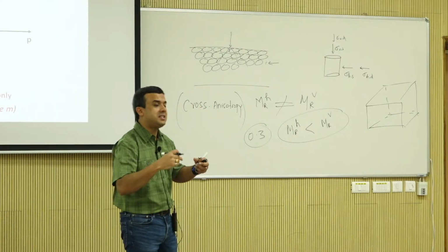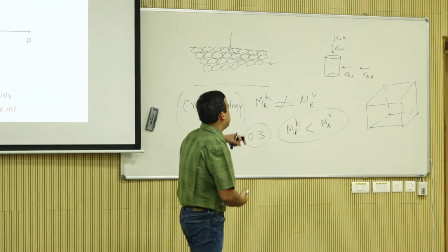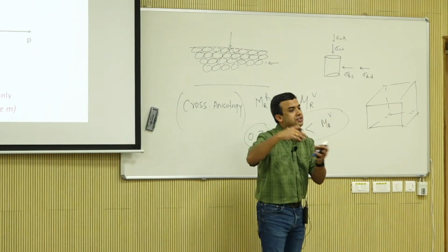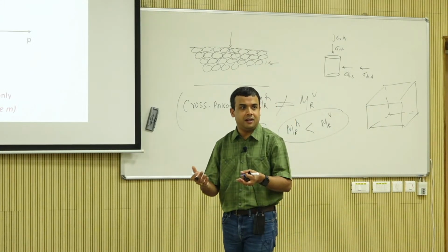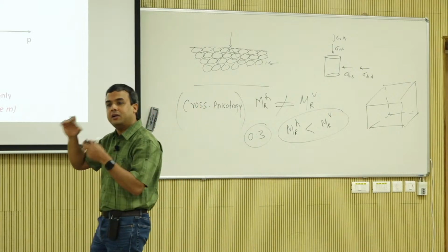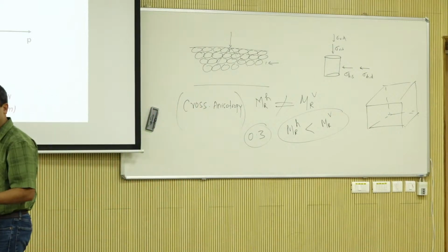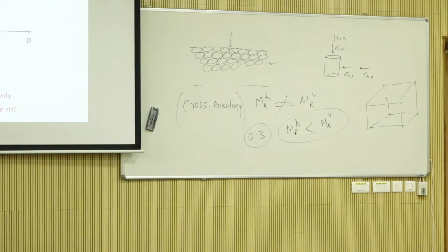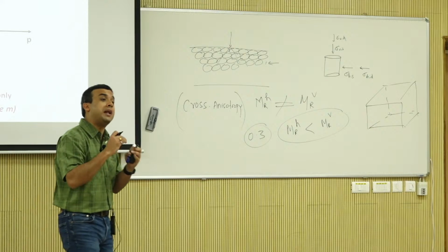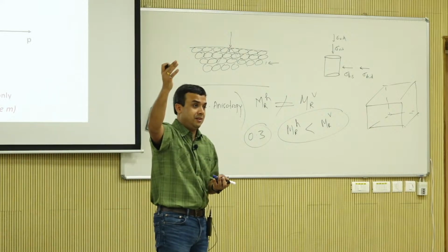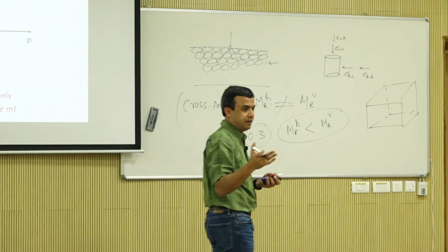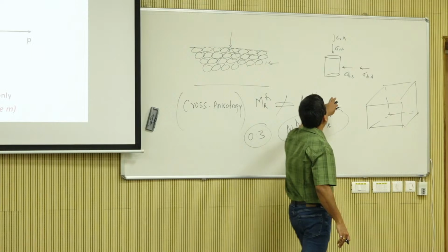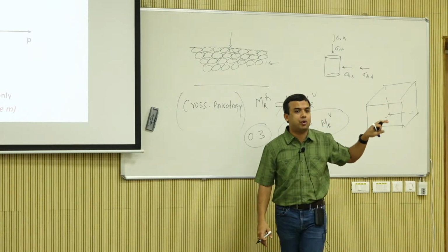If you're overestimating the stiffness, then sigma over E is your strain, so you are underestimating the strains. If you're underestimating the strains, you are underestimating the pavement responses, and so you are now overestimating pavement life, because your prediction functions are based on that, right? That is the whole reason this setup was designed.